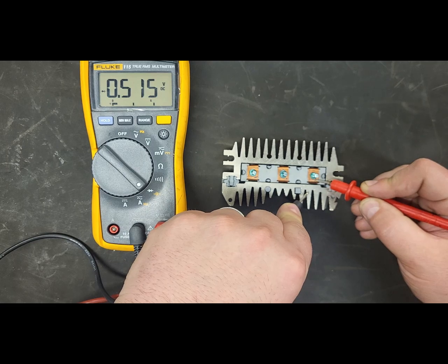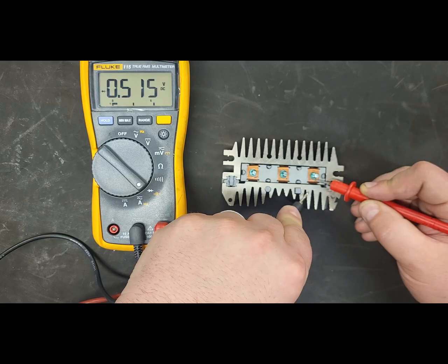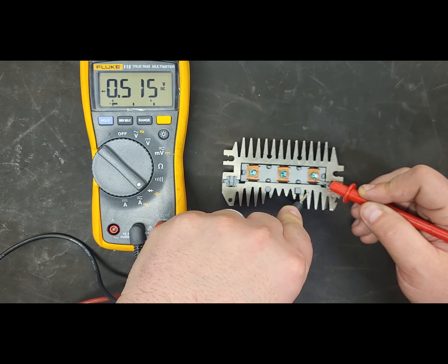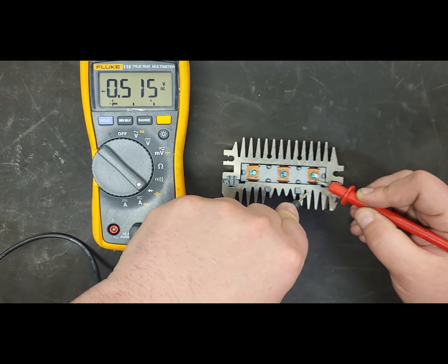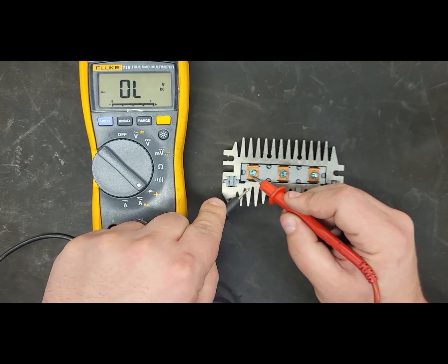That's the amount of voltage needed to activate that diode. That's going to turn it into a one-way check valve with that much voltage. That's a pretty good number. Anywhere in the range of 0.448 up to about 0.55 is a pretty good range. I'll go through and do that with all of these diodes.